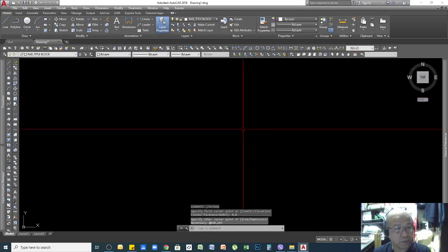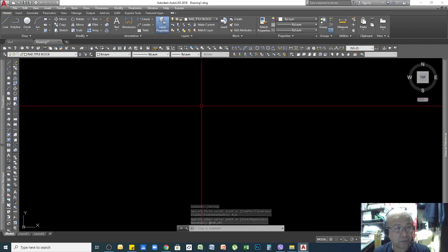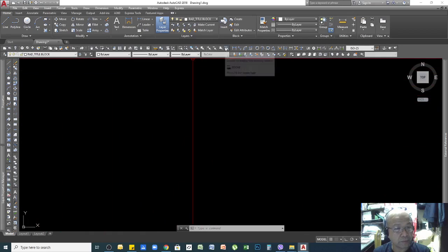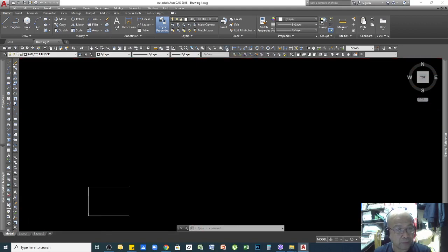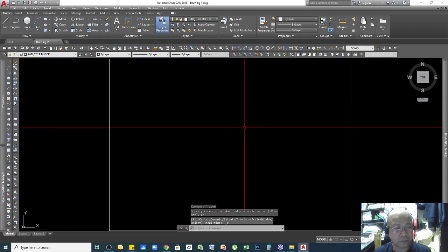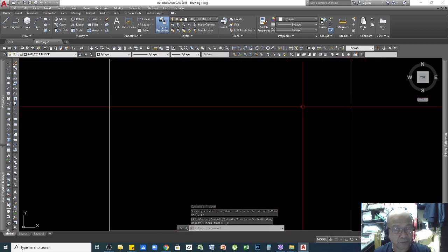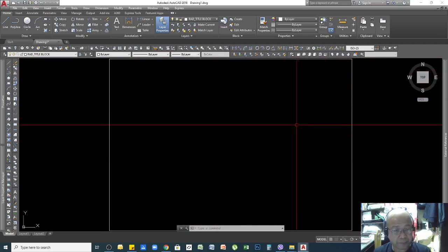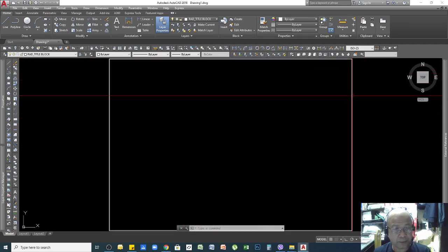Okay, so you cannot see the rectangle that you created. In order to see that, you go here. This is the zoom function, where it will show you the whole space or area that has drawing. So just click this one, and then there you go. The space that you created is here already. So this is the paper space that we've set up.